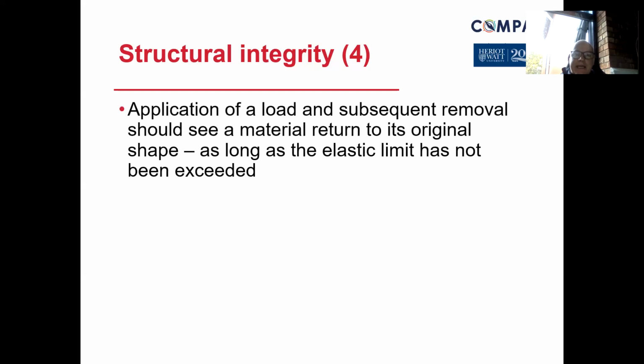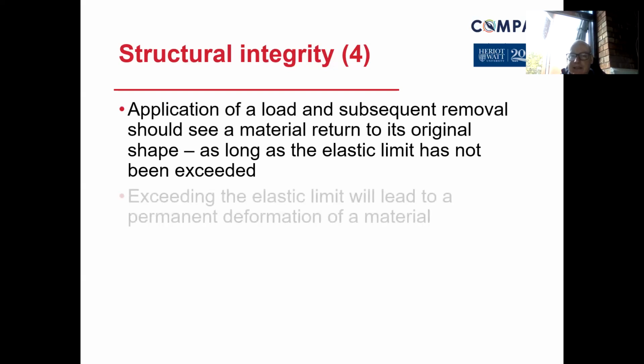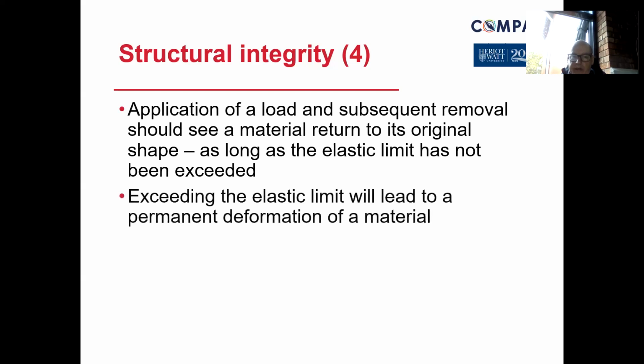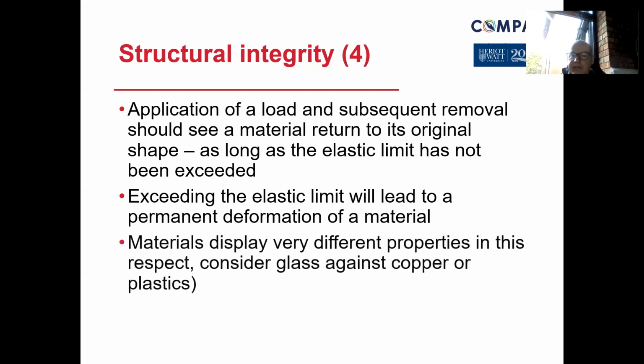Application of loads and subsequent removal should see a material return to its original shape as long as the elastic limit has not been exceeded. So that's the general theory there. Exceeding the elastic limit will lead to a permanent deformation of the material, and materials display very different properties in this respect, considering glass against copper. So glass will shatter, copper will stretch and eventually give way.